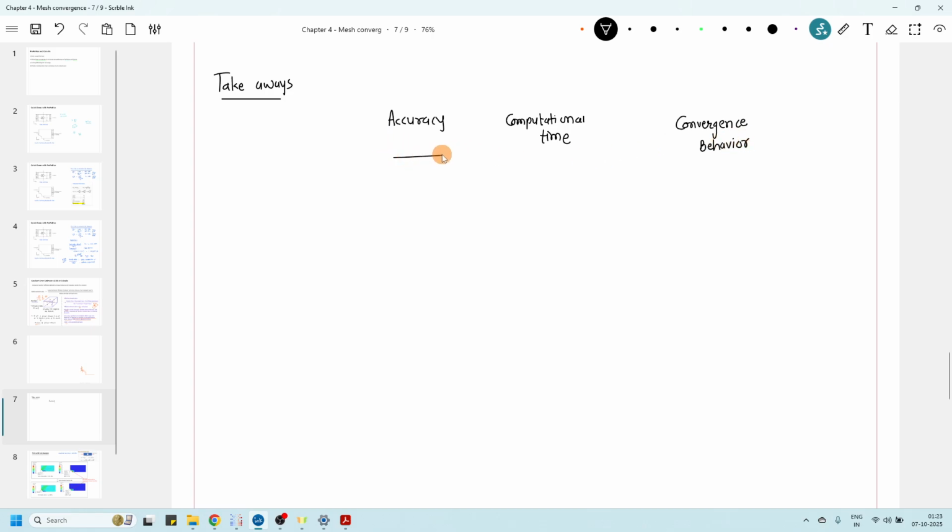So this example we have shown for second order tet elements, but the mesh guidelines apply universally, for any element type, hex elements as well. If we use a too refined mesh, too refined meaning more than required, this is where most engineers make a mistake. They hit convergence issues, and the first thing they think is to refine the mesh. That is not correct. If you refine the mesh, your convergence behavior will become even worse.